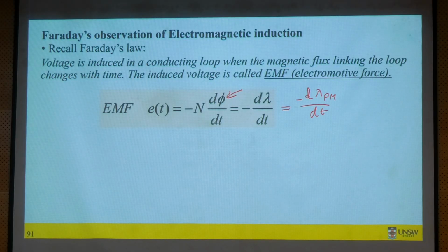In the case of a conventional synchronous machine, it's the field current which will produce this flux phi, right? In the case of an induction machine, this flux will be the mutual flux between stator and rotor. Stator flux induces this flux in the rotor, okay?